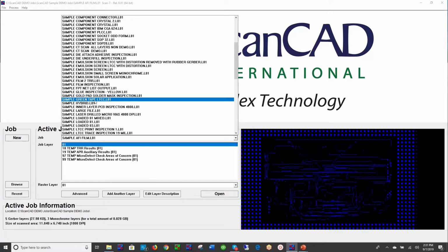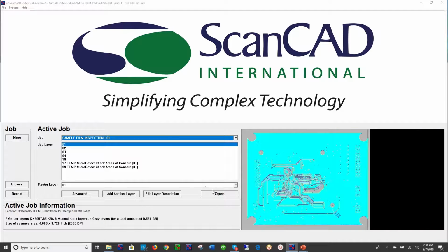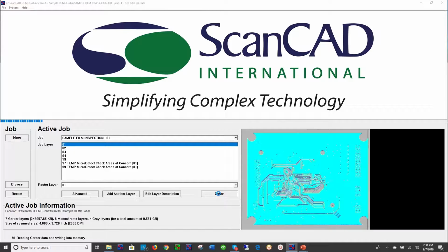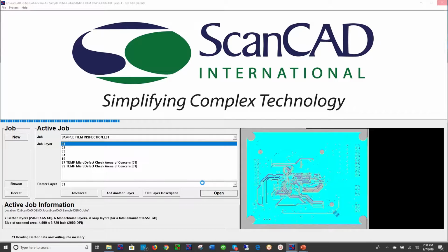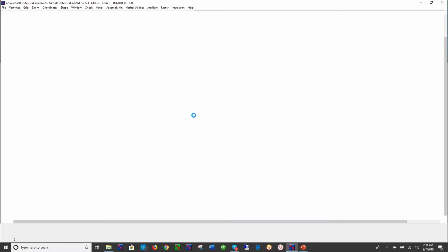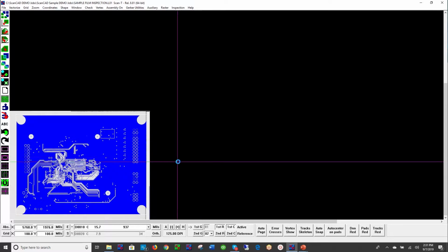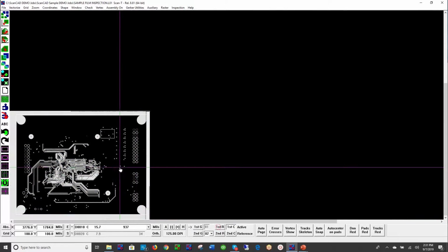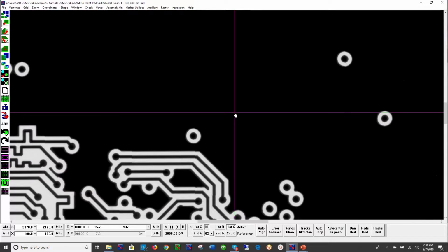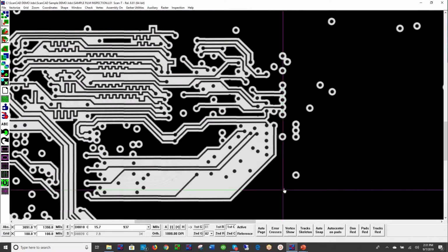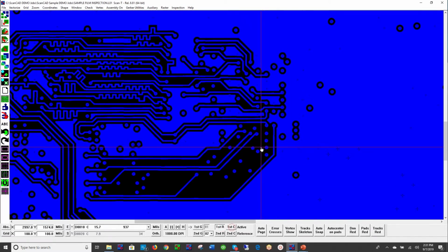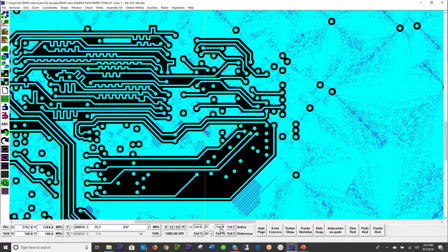Let me now share a film inspection that is using CAD data. So we'll open this up. And again, the same process you saw a minute ago: we import the green CAD data, we scan the part in color, and we overlay. So in the process of importing this job right now. The job is scanned in color, and obviously a film is monochrome anyway, so we'll just color separate on the film. We get this monochrome image. We overlay the CAD data, which is the green data.